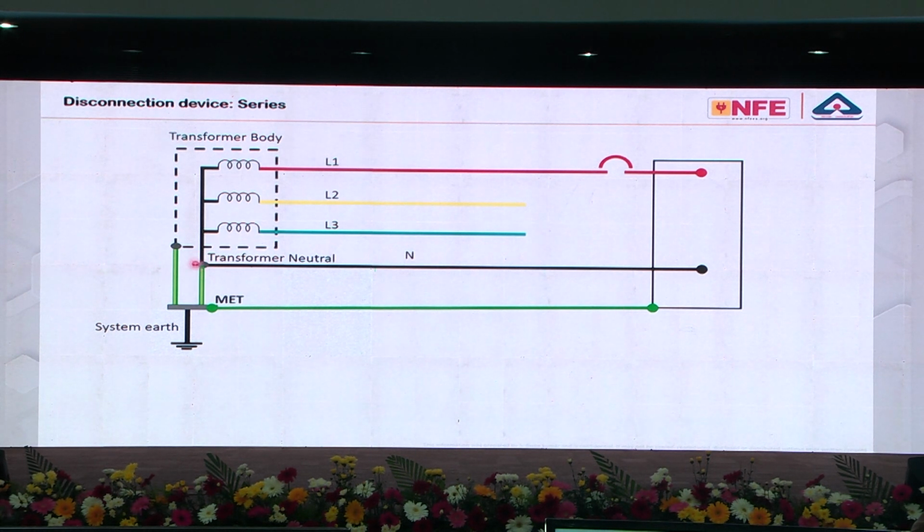It starts from the transformer neutral, and every equipment body or a group of equipment is connected to this particular conductor. Now in this particular case, imagine there is a fault. Often we show this picture, which shows the phase conductor insulation has broken and it is in touch with the body of the equipment. Now the fault current starts flowing.